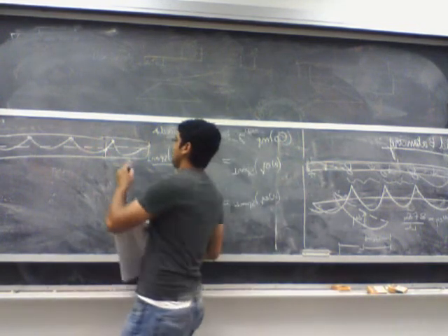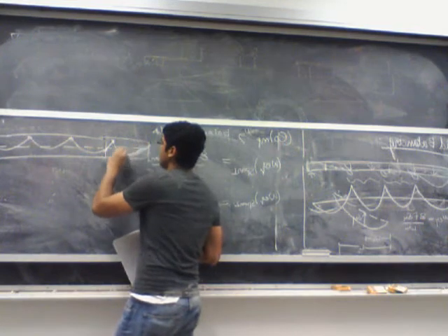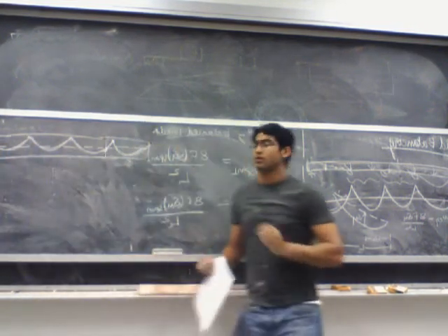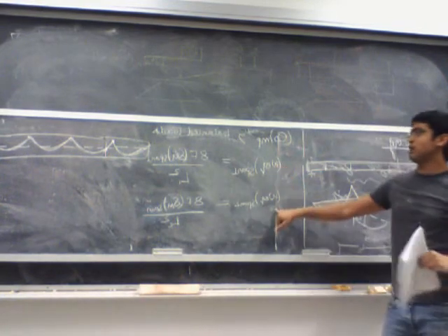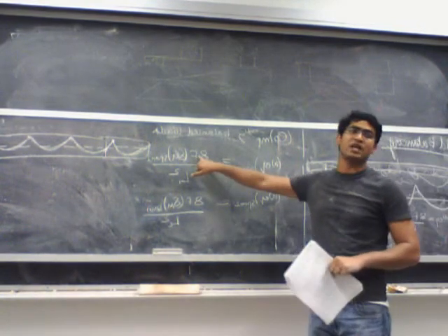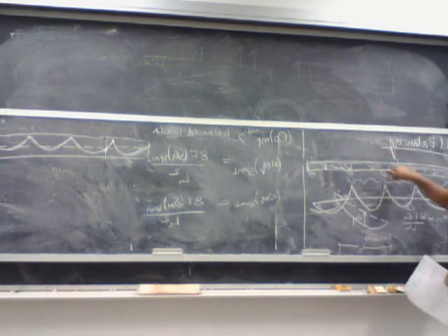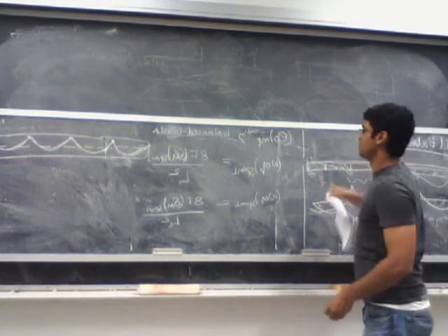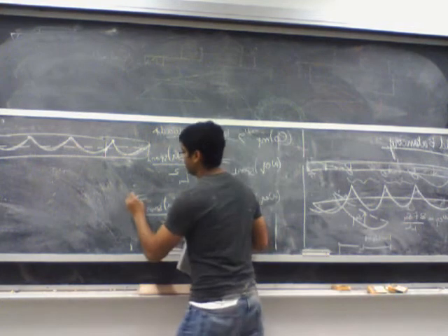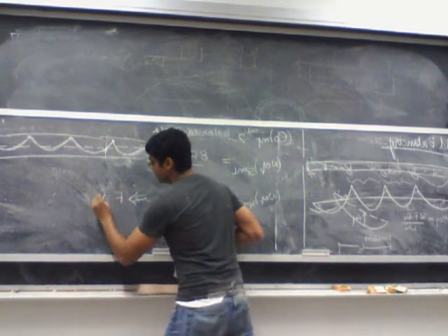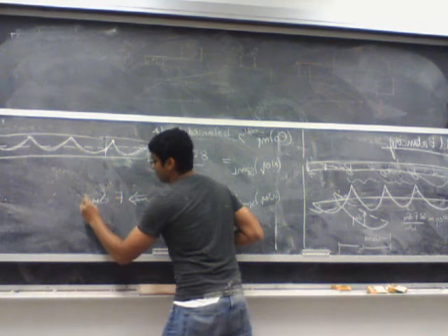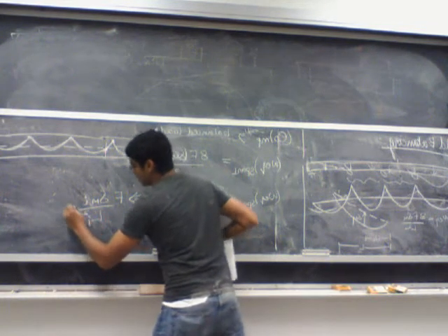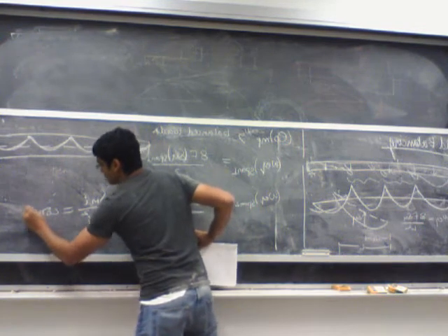Okay. Now what you need to do is find out what the actual profile is in all 3 of them. Now based on the omega equivalent, I know my F is the same. If my omega equivalent is the same on each one of the spans, that means that my F times delta M of span i divided by Li square is actually a constant value, right?